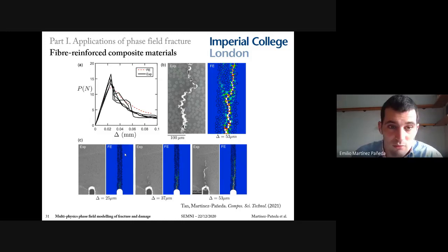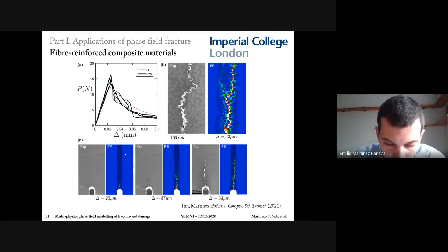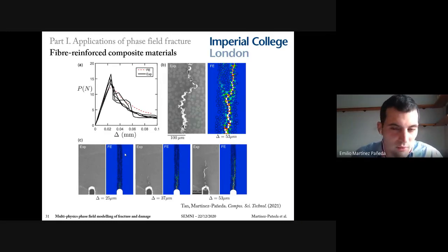The ideas are similar to cohesive zone models in the sense of having a fracture energy. On the other hand, cohesive zone models do require that you know exactly where your crack is going to propagate. So the phase field gives you a bit more freedom in that sense, and it also seems to be more computationally robust. At least I haven't encountered so many convergence problems. In regards to XFEM, while I very much enjoy working with it, it was a bit of a challenge to take XFEM to 3D. With phase field, you can use the same code for 2D and 3D, so it's completely straightforward.